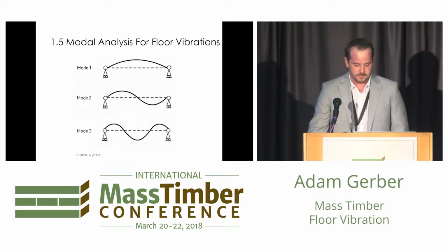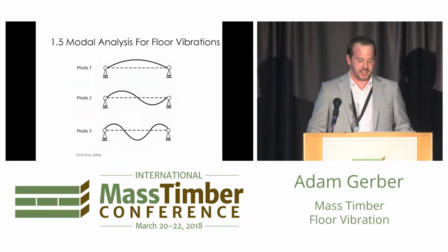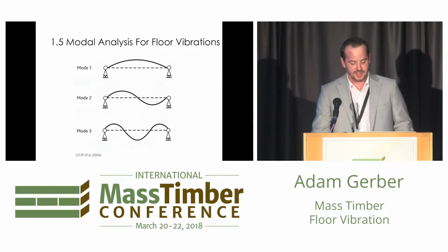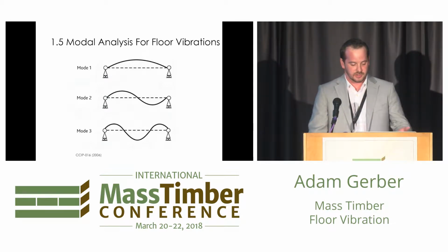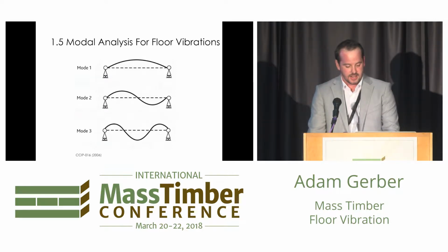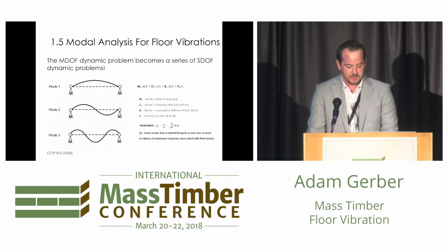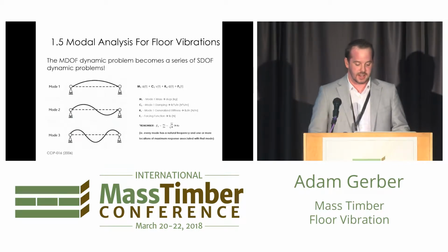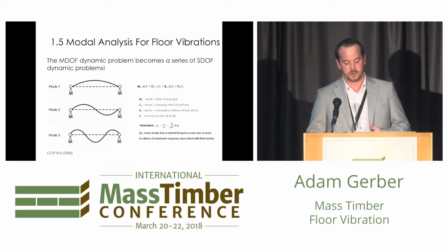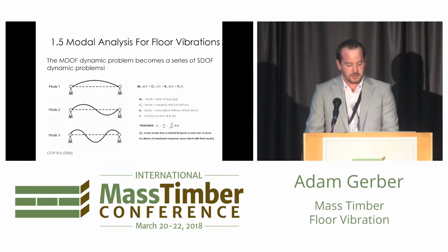Of course, real structures have multiple modes, with varying degrees of energy, going from the lowest energy mode, the first, to increasing energy. You get all sorts of mixes of behavior. Essentially, the take-home is that every mode has a natural frequency and one or more locations of maximum response. And the beauty is that we can solve each mode individually and superimpose all the results together to simplify the problem.